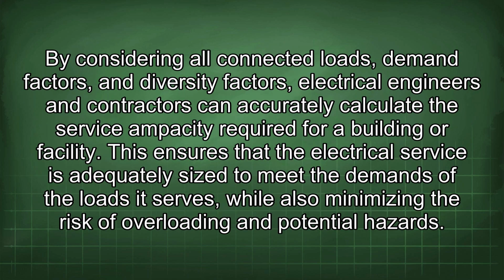By considering all connected loads, demand factors, and diversity factors, electrical engineers and contractors can accurately calculate the service ampacity required for a building or facility. This ensures that the electrical service is adequately sized to meet the demands of the loads it serves, while also minimizing the risk of overloading and potential hazards.